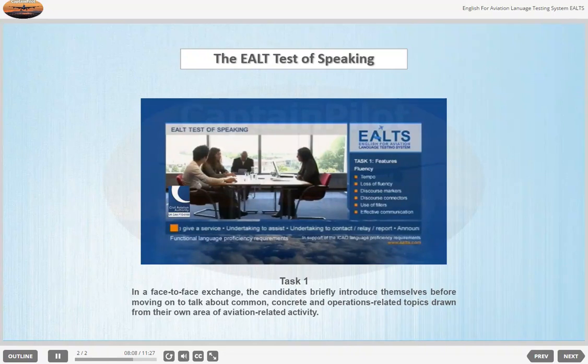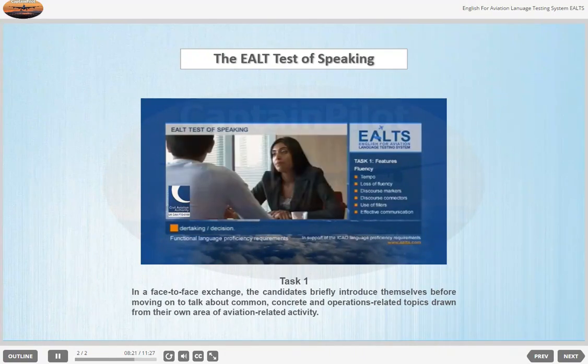This is for a low power and low drag approach. For this, we instruct aircraft to fly between 210 knots and 240 knots during approach.